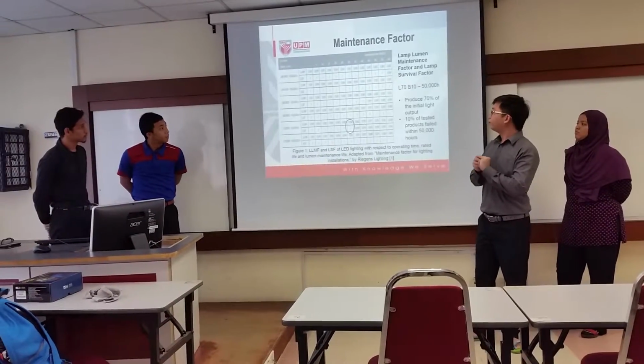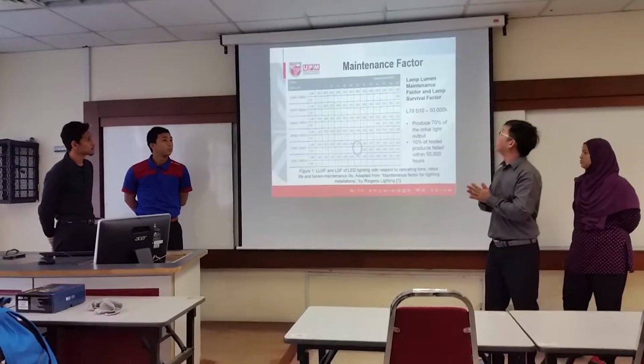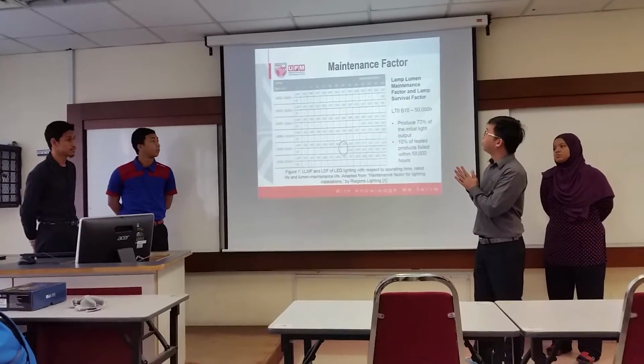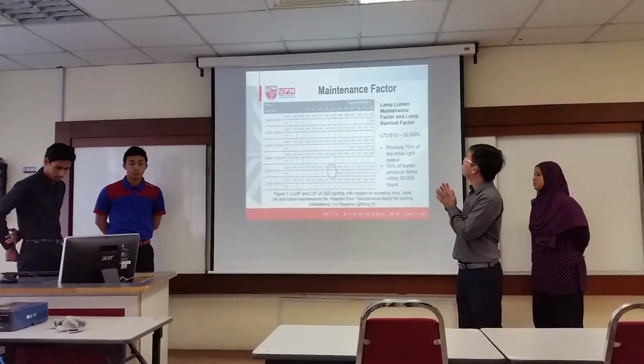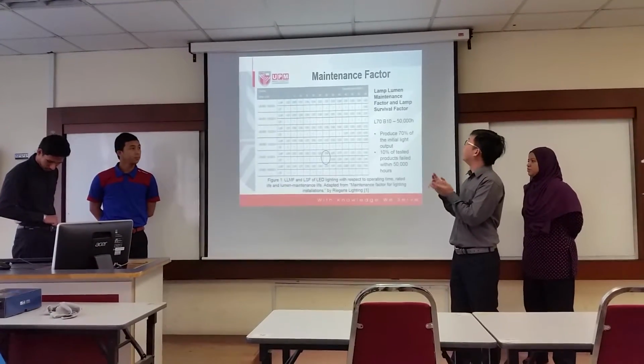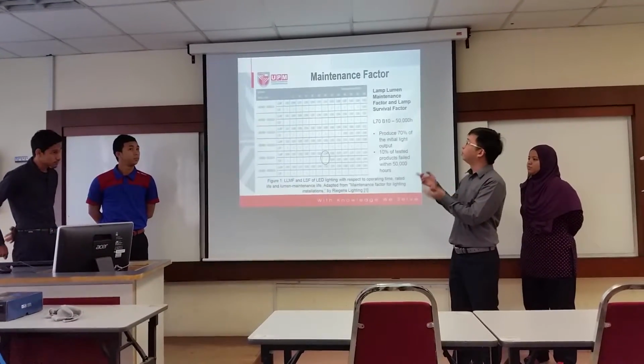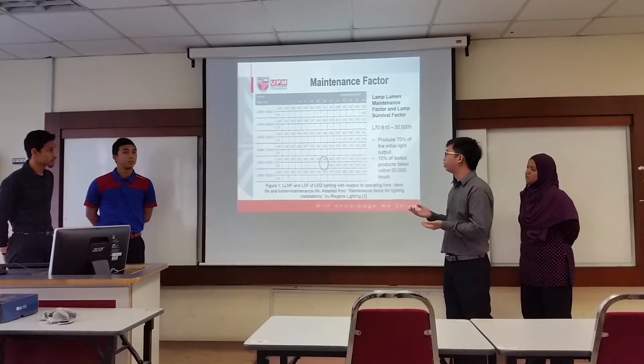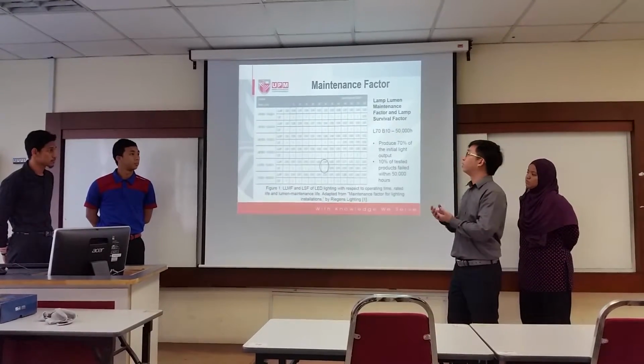First, the maintenance factor. As you can see in the table, the lamp luminance maintenance factor and the lamp survival factor are provided by the manufacturer, Regions Lighting.